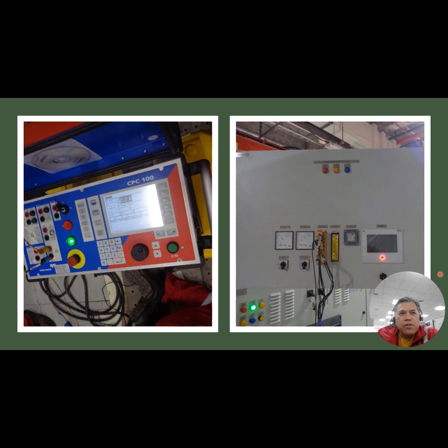During the FAT, you cannot test some of the equipment for environmental condition, but during the SAT we can identify the temperature and humidity of the equipment. Then we do the testing for electrical, safety and controls: proper wiring, and any overload protections, CT, VT. Any loop testing is to be carried out as well. So those are the activities of our SAT.